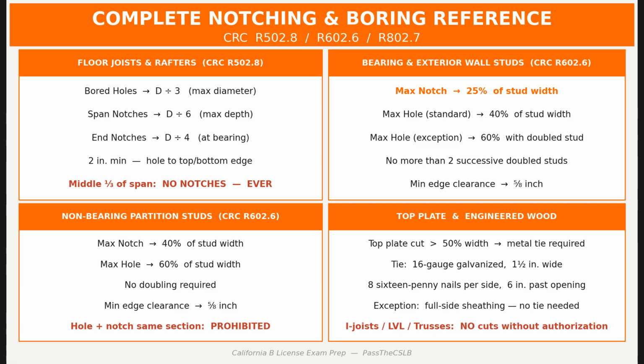Engineered wood, I-joists, LVL, glulam, structural composite lumber, prefabricated trusses, no cuts, notches, or bored holes without written authorization from the manufacturer or a registered design professional. No fractions, no percentages, no field exceptions.